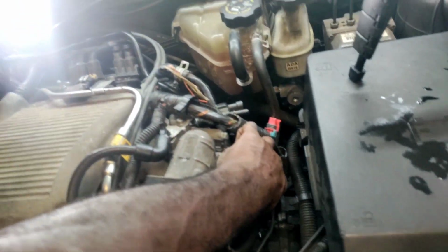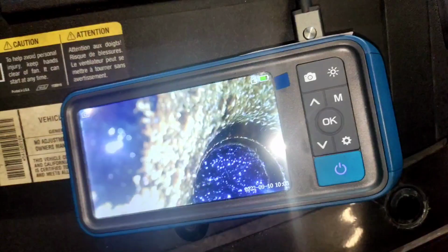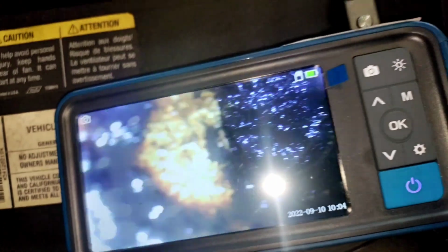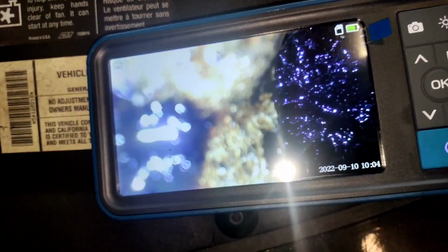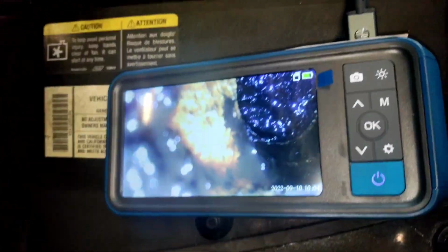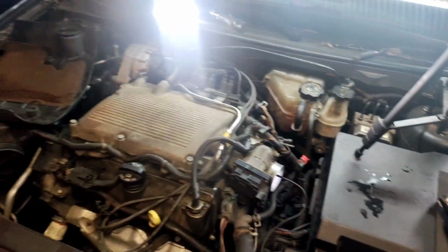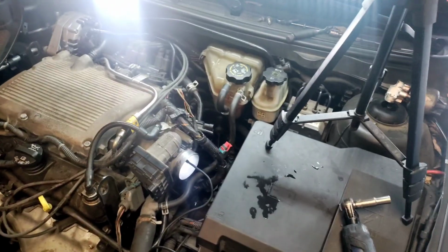All right, I had to change some plans up because I couldn't get any detail with that Harbor Freight camera, but there's the port for the EGR valve and it's blocked. So that's where I'm going to be trying to clean up everything. I'm right inside the throttle body, about a couple inches back. So if I can get that obstruction clean, we'll be good. I would rather just leave the original throttle body on there so I wouldn't have to change that harness. Fudge cake.